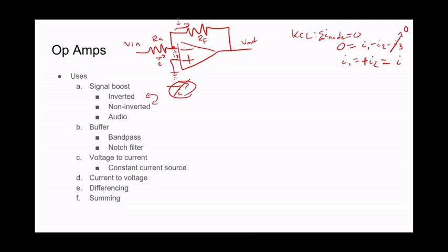Now that we know we have I flowing through this circuit, I'm going to simplify this again to just I in and I over here. Now we can use Ohm's law, which states that voltage equals I times R. The other rule we're going to use is rule number 2, which states that the positive and negative terminals, or inputs, must be equivalent.